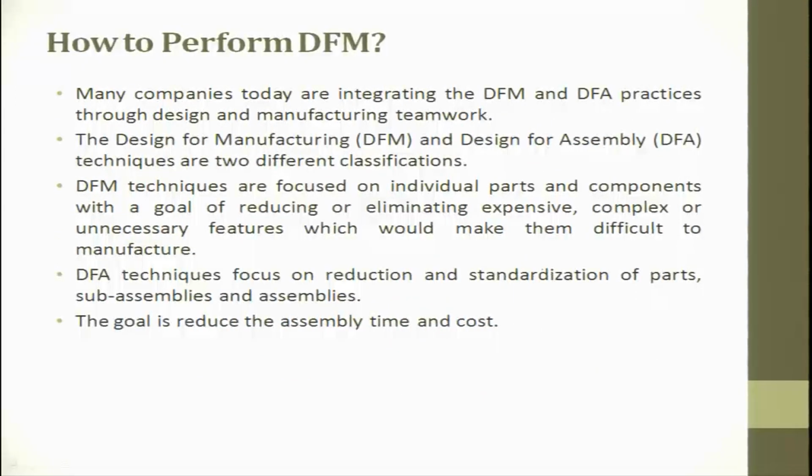How to perform DFM? Many companies today are integrating the DFM and DFA practices. DFM is design for manufacturing, DFA is design for assembly. Assembly is a separate thing. So, when you talk about manufacturing, there are 2 approaches, I have told earlier also. It is part producing and then assembly. So, assembly is a subset of manufacturing.